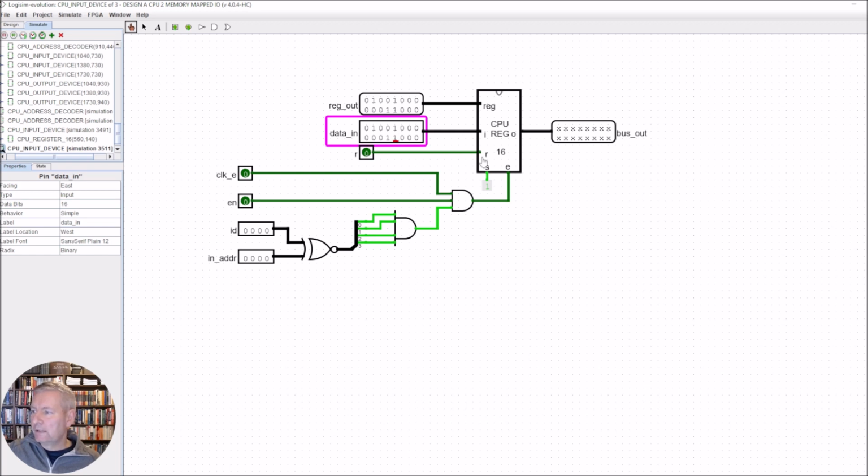And we've got a reset pin here. Now all we're going to be doing with this is writing data onto the bus. So we're reading data out of it onto the bus. We won't be writing into this device. So we can set the set pin to a high, and then all we're going to be doing is enabling this information through onto the output. So in effect it's like a transparent latch now, and it's controlled by this enable line.